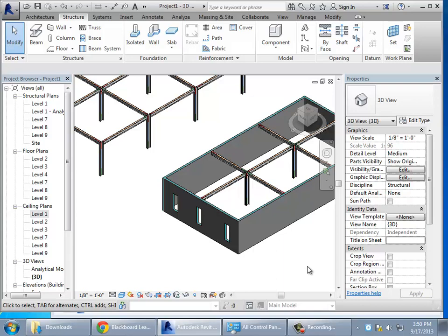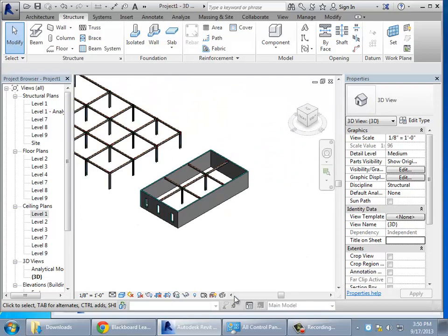Actually, in your structure, I was looking at the pictures. To me, they look like they were 8 feet apart. What's the distance between those intermediate beams or the joists? On your structure, you want to measure that? We'll go ahead and put them in around every 6 feet, something like that. Smaller beams are going to span between that distance. Okay, so let's take a look at that.